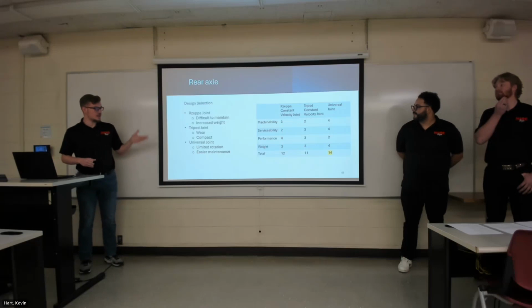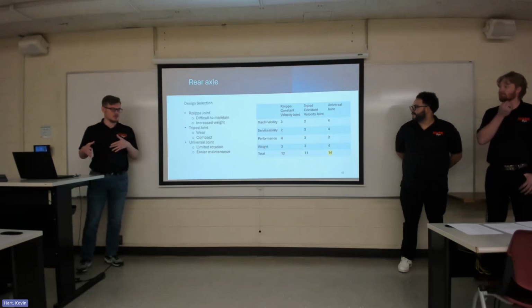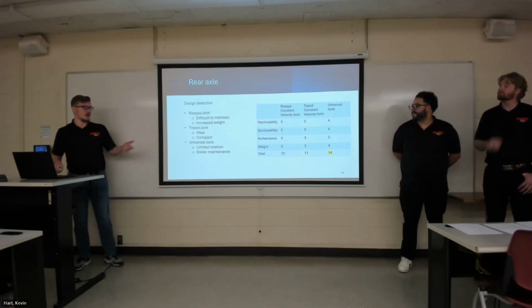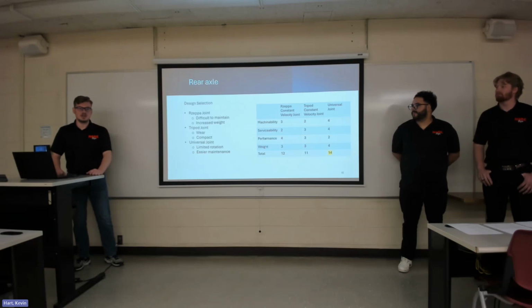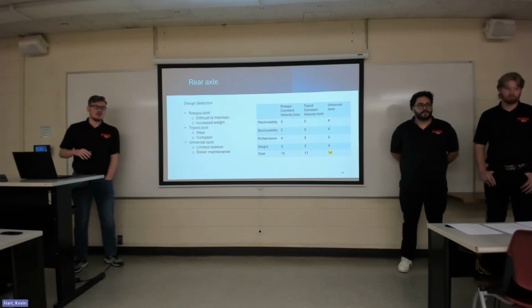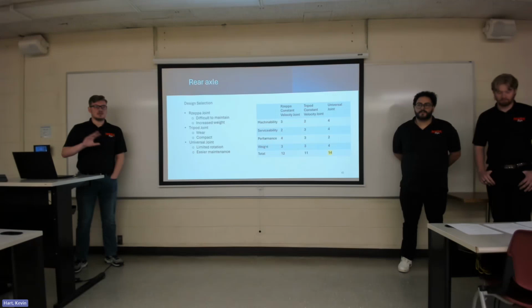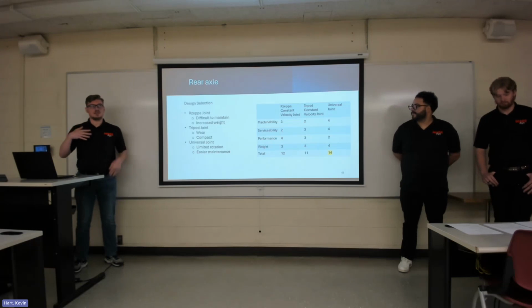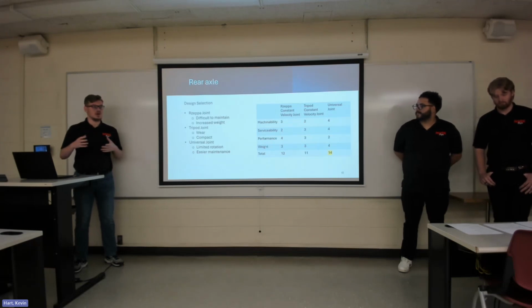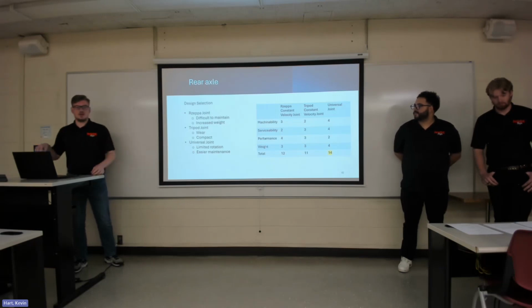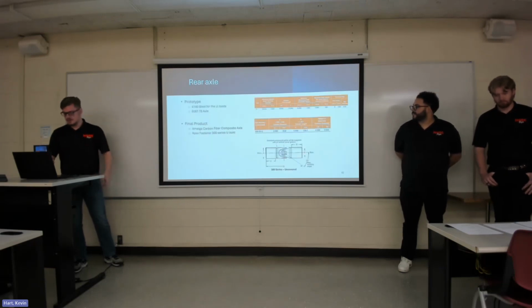However, there is a drawback to these U-joints. They have limited articulation for angles and aren't able to go to the kind of extent that those CV joints were able to, which puts a restriction on how long we can make these axles in our final designs.